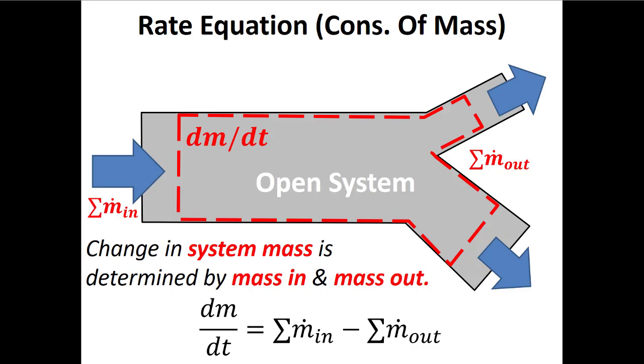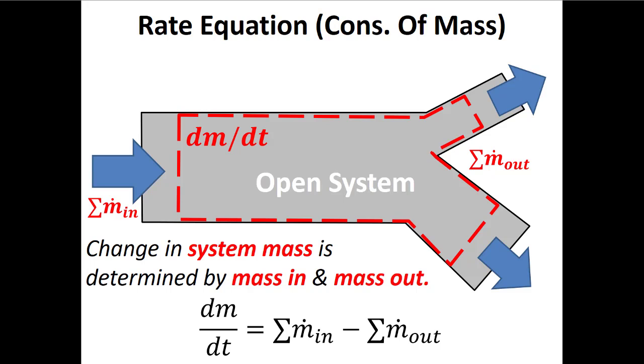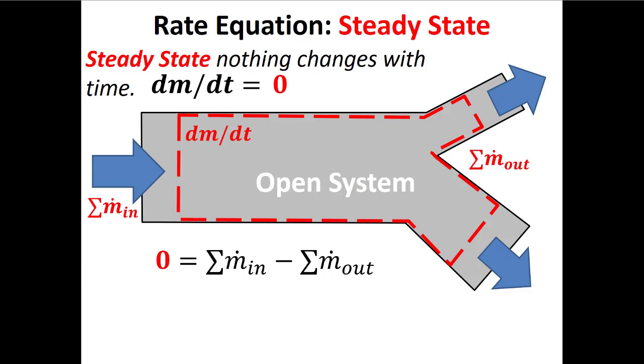When we use closed systems, we're often interested in how something in the system is changing over time. When we use open systems, our subscripts are going to depict not moments in time, but locations in space. So here there's one inlet and there's two outlets. So what are the mass flow rates at the inlets and the outlets? And what are the states of whatever material is flowing through my system at the inlets and the outlets, right? Because you can imagine something like an air conditioner where it takes hot air in from outside and blows cold air into your house. If it's a window air conditioner, right? There's this change in the properties of the air as it moves through that system. So we'll be able to talk about how the energy has changed as we move through that system.